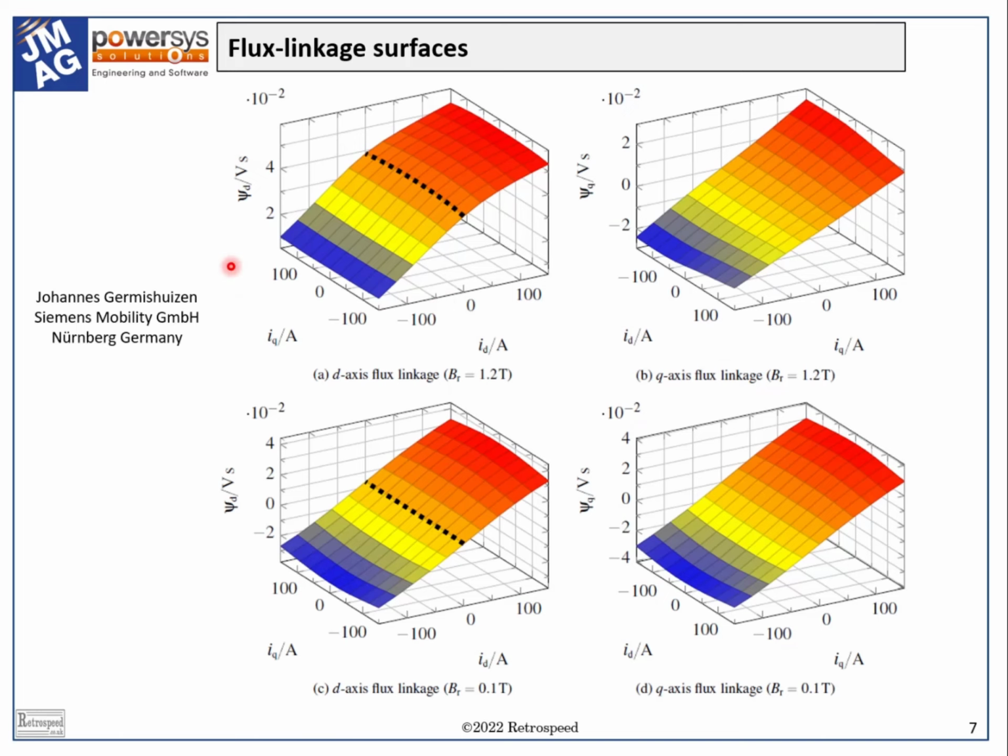But consider how we would use this data to improve the design of, say, the windings or the disposition of conductors within the slots, or indeed any other detailed aspect of the machine design. Would we do it by countless repetition of the finite element calculation in a series of numerical experiments?